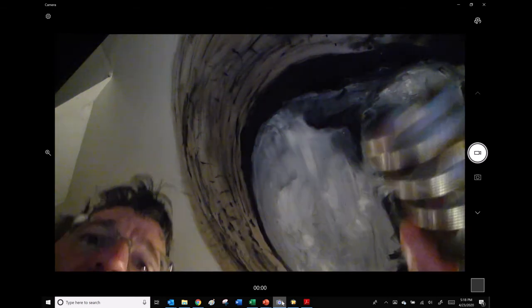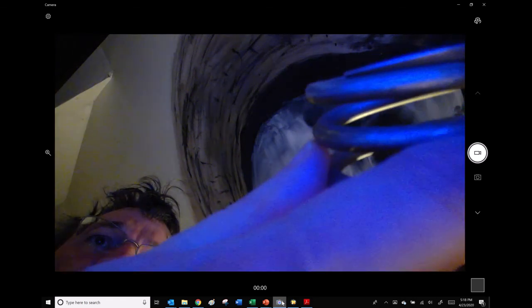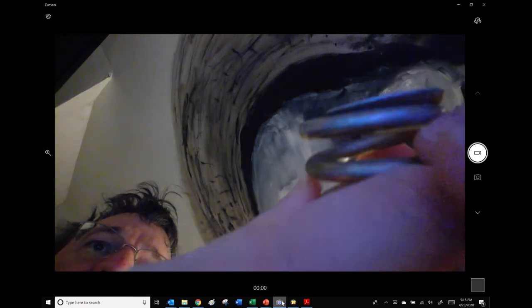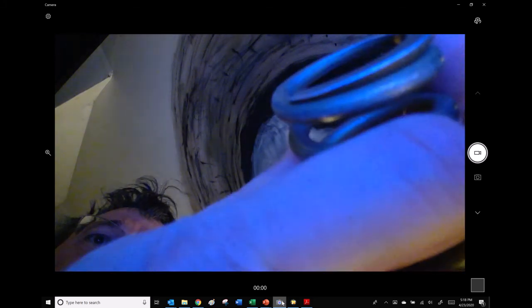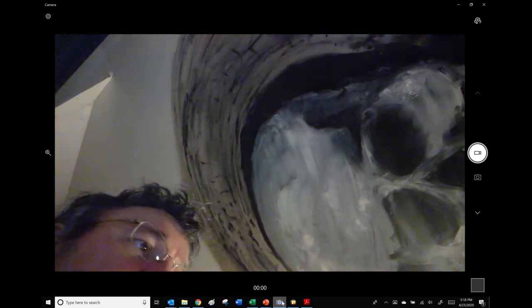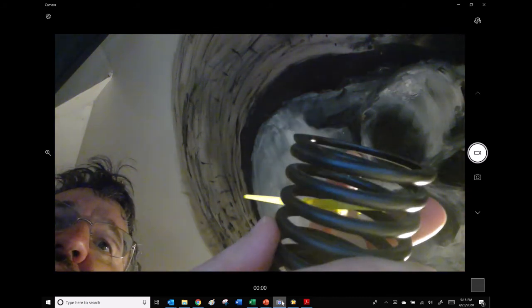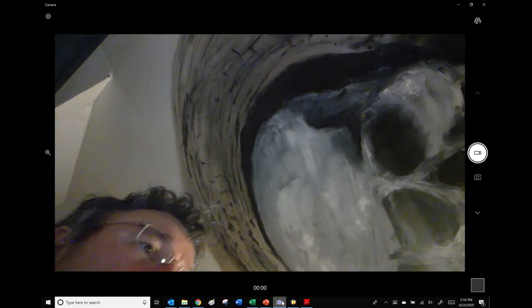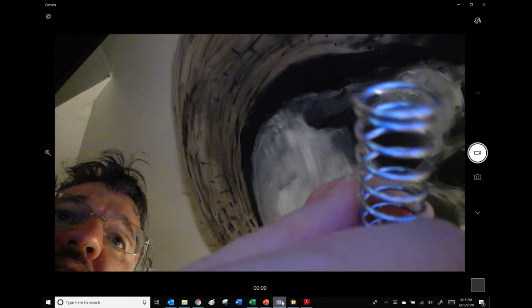Here's one where they did a lot more grinding onto the piece, right? You can see that they closed the thing, right? So it doesn't have the same gap right here as it does in the next coil down. This has a much more of a flattened area to lean against. This one, I thought this was a much larger diameter spring right here. And so you could see there's that flattened area, but also you could see that it's closed. Right? Whereas this guy right here, they didn't bother. They just closed it, right? They didn't bother to grind the thing off.